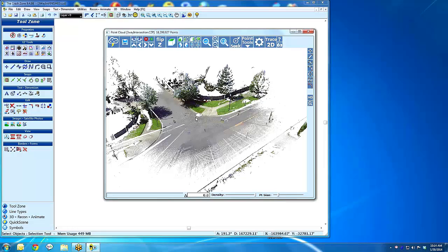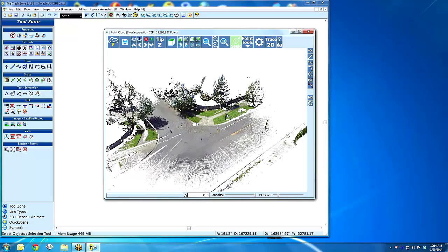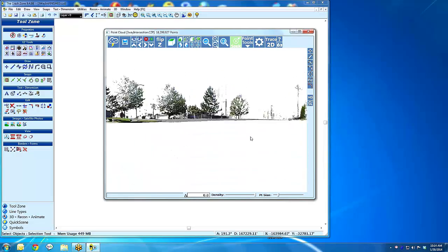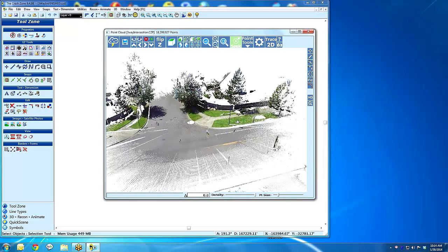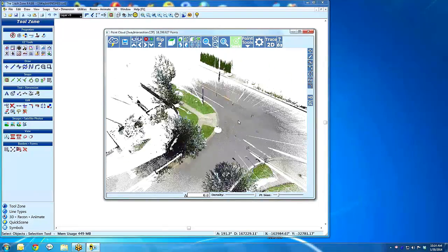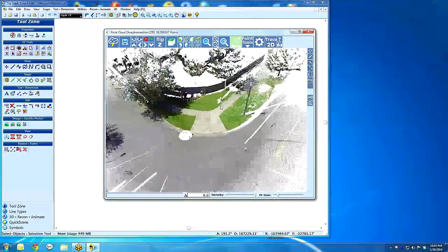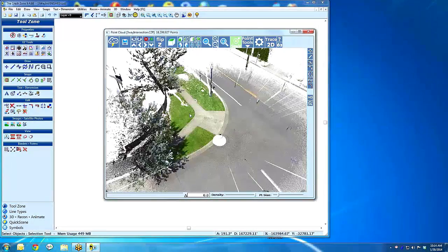So the neatest tool we have for doing that is Seek. This is kind of the king of the navigation tools. You click on Seek, and you pick the area, this is really setting a rotation point. You click, let's say, right there. Once I do that, everything I do revolves around where I clicked with Seek. So I can rotate, but you notice it's zeroing in around that.